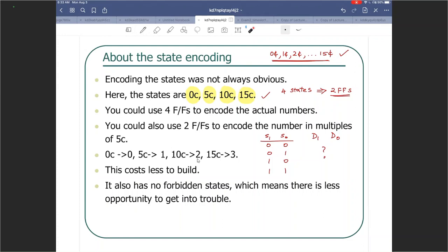I'm going to have the same problem that I had while designing counters with random power-up states, which are skipped states. In that, if I skip a state, if I randomly power up in that state, I am going to have various possibilities. I may come back into the counting sequence. I may never come back into the counting sequence. That is dependent on how I implement that counter. So the same problem over here.